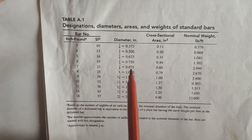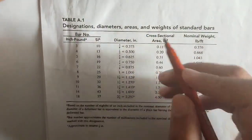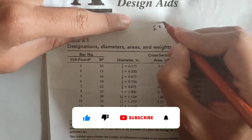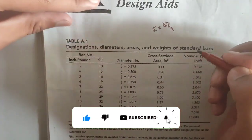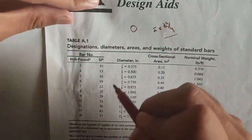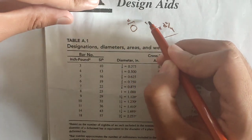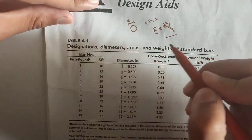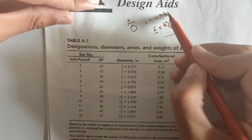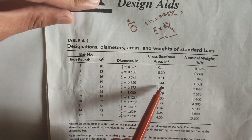The next column will be the cross section area. What you will have to do is pi d square by 4. This will be the formula because bars are circular, and d is the diameter. Pi value is 3.14. You will put d, for example, the diameter is 0.75, 0.75 squared divided by 4, and you will get its area, which is 0.44.